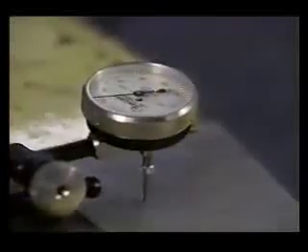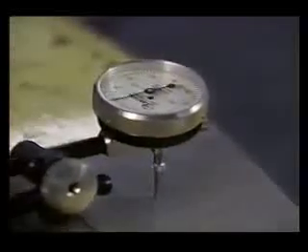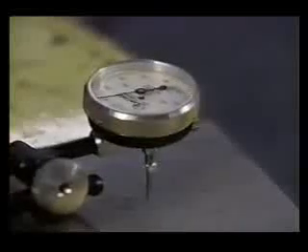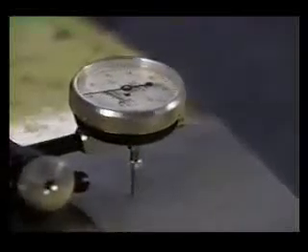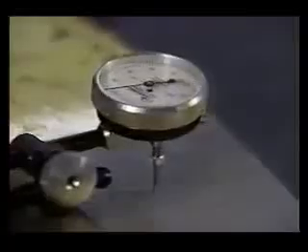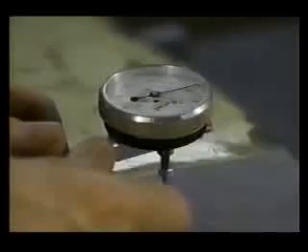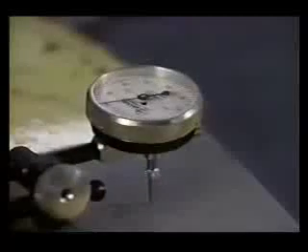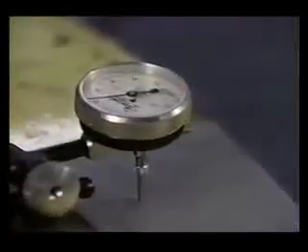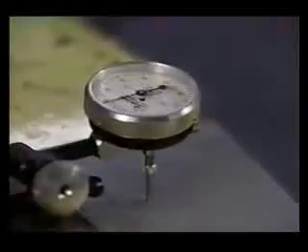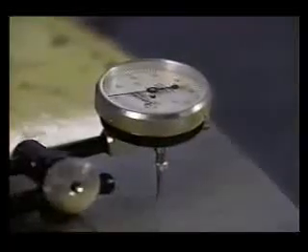You can use a depth dial gauge to measure the depth of the corroded areas. To properly use this tool, you will need to take readings both in and around the corroded area. First, you must zero the gauge by measuring a non-damaged area. Then take a reading from the deepest pit. This reading represents the amount of material lost to corrosion.